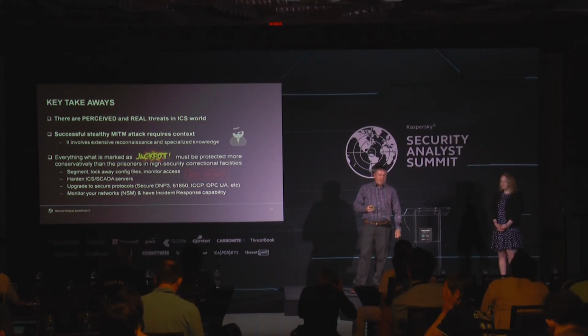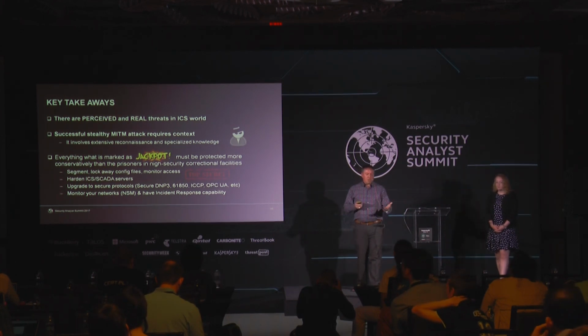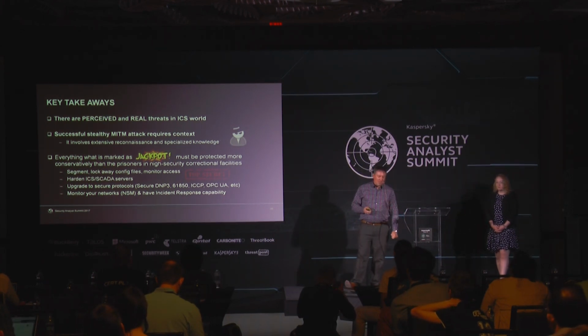Everything that's marked as a jackpot has got to be protected. So segment, lock away your config files, monitor access, harden your SCADA servers, upgrade to secure protocols, secure OPC being one of them, monitor your networks, do network security monitoring, and finally, have an incident response capability.